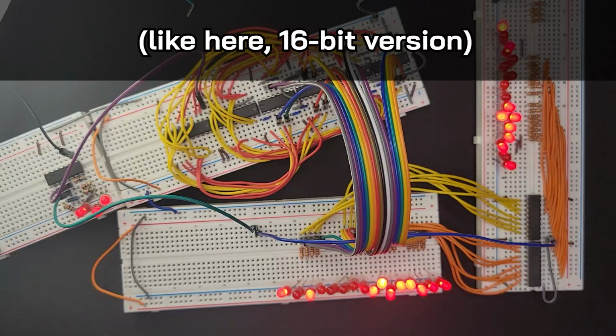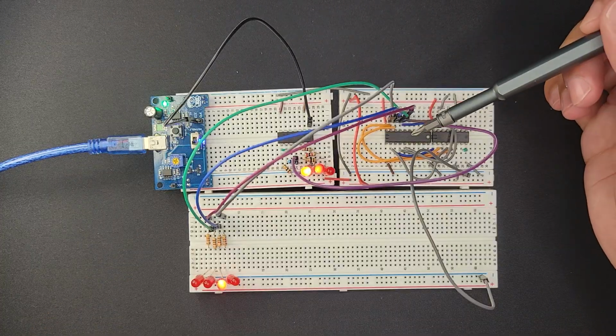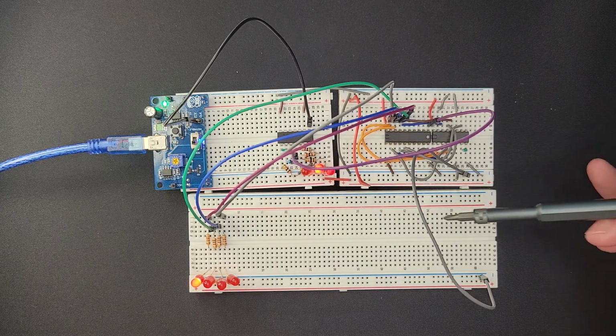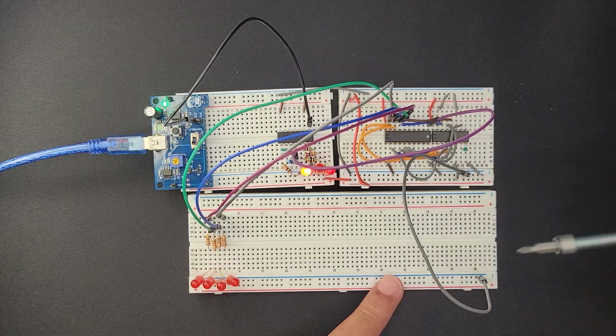So I'll probably just add the memory address register right here. The register I'm using here is a 574 for the instruction pointer or the program counter to keep the data. So I'm going to use one more of these. Ultimately, it will be 2 because this is an 8-bit register. So I'll have 2 of them for 16 bits and then pull the data from the instruction pointer when fetch occurs. At least that's the idea.